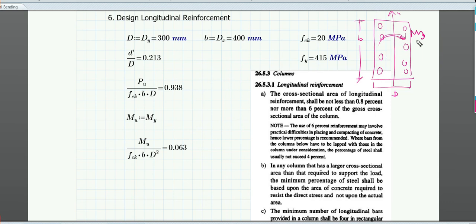A rectangular column has certain advantages for a uniaxial moment, where My should be taken care of by providing reinforcement, but Mx is already being taken, probably not required, because in this direction your width is less and the moment of inertia is also less, so you can relate everything.